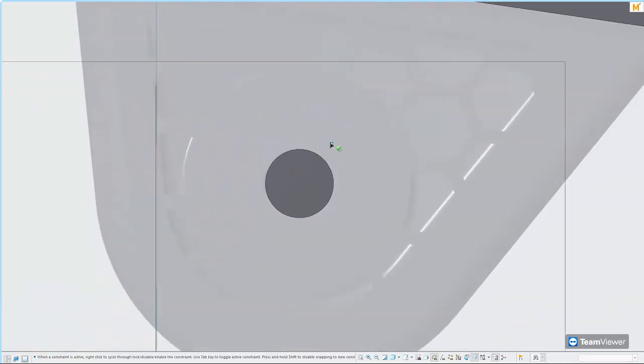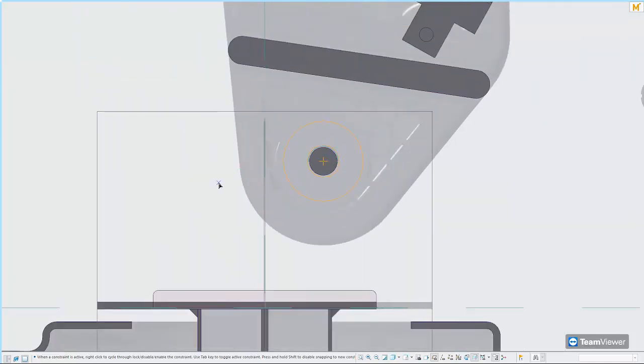Another great capability that introduces us to tip 3 is how to get your designs out quicker with the improved Sketcher capabilities. And to start us off with that is automatic references. I don't need to pick my references, but just by hovering over entities, Creo will now present me with a list of references available for me to work with. Here, by selecting this circular arc, it's presented me with the edge as well as the center point. So let me pick the center point and let me model my particular shape. Very quick and simple when working in this environment.